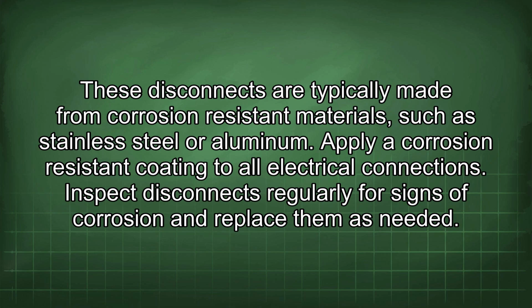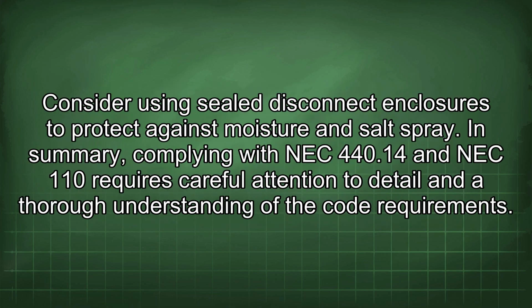Apply a corrosion-resistant coating to all electrical connections. Inspect disconnects regularly for signs of corrosion and replace them as needed. Consider using sealed disconnect enclosures to protect against moisture and salt spray.